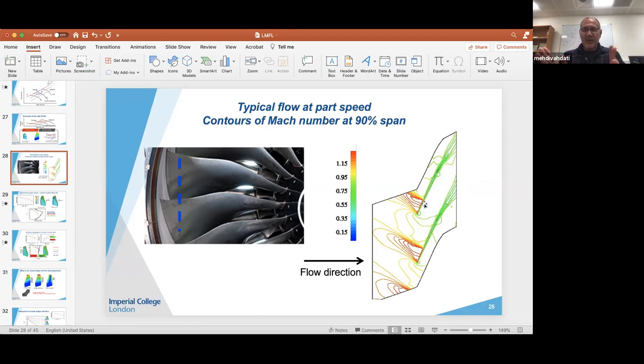So consequently, you could be closing the nozzle or opening the nozzle, and that plays quite an important part in flutter. The other thing I found quite important is the area of the covered passage, i.e. the area which sits between two blades, with metal on the top and metal on the bottom. These two are quite important because they determine the shape of the passage as the blade vibrates.